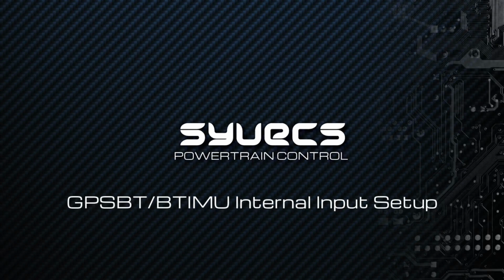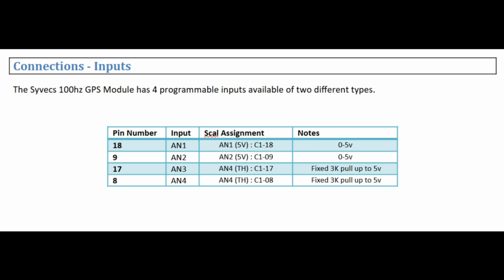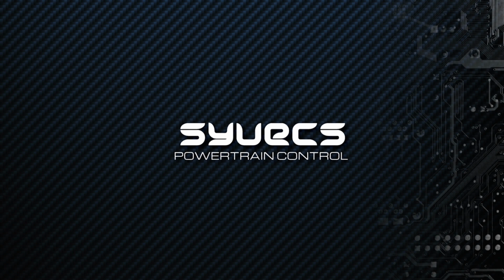The Syvecs GPSBT and Syvecs BTIMU both have 4 configurable analog inputs present on the hardware. These can be utilised in 2 methods. First, via the control of the mobile application, and second, via the internal processor on the device. If you're wanting the input to be utilised all the time and transmitting whenever the unit is powered up, then you need to do it via the internal hardware and the SCAL programming.